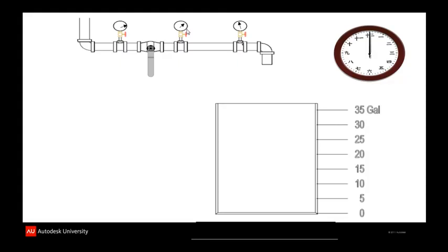And then the single outlet gauge has been replaced by two gauges here. This is the upstream gauge I'll refer to it as, and the downstream gauge I'll refer to it as. And the difference in pressure between those two gauges is the friction loss. We've also replaced the sprinkler head with just an open pipe, and we've kept the container to collect our water in, and we've kept the clock to measure the time with. So when we open the valve at various calibrated amounts, we can create a friction loss and measure the flow.